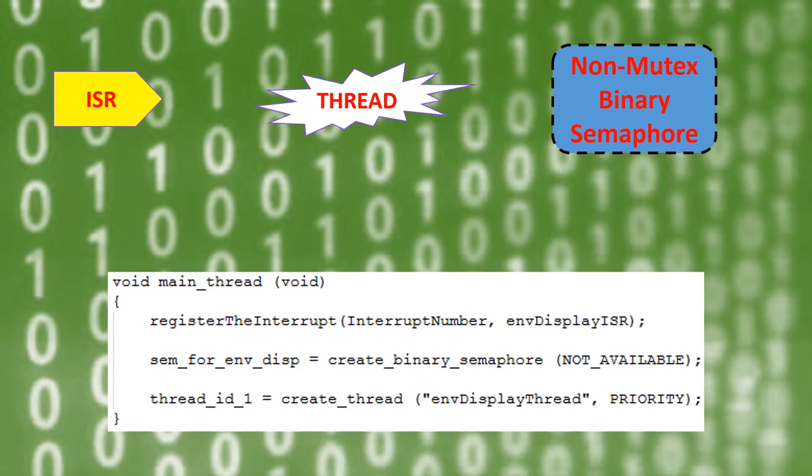This API takes as its first argument the hardware interrupt number you want to register, and another argument is the function name, or ISR name, which we need to define. This would be our ISR function name, which gets called when the hardware interrupt is triggered.